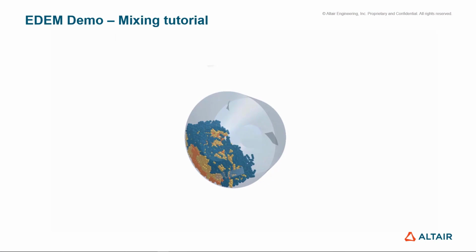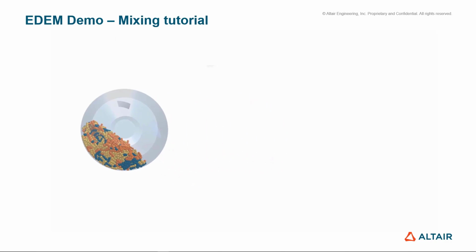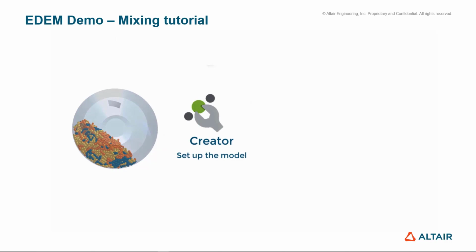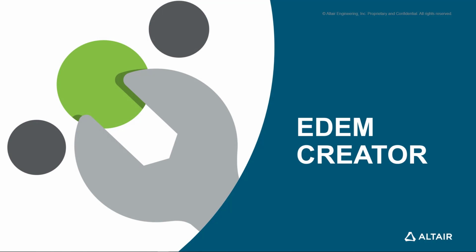For the EDEM demo, we're going to do the mixing tutorial. And in this demo, I'm going to present the three different components of EDEM, starting with the EDEM Creator, where we set up the model, then the EDEM Simulator, where we run the model, and finally the Analyst, which is the post-processing section of EDEM. Let's start with the EDEM Creator.